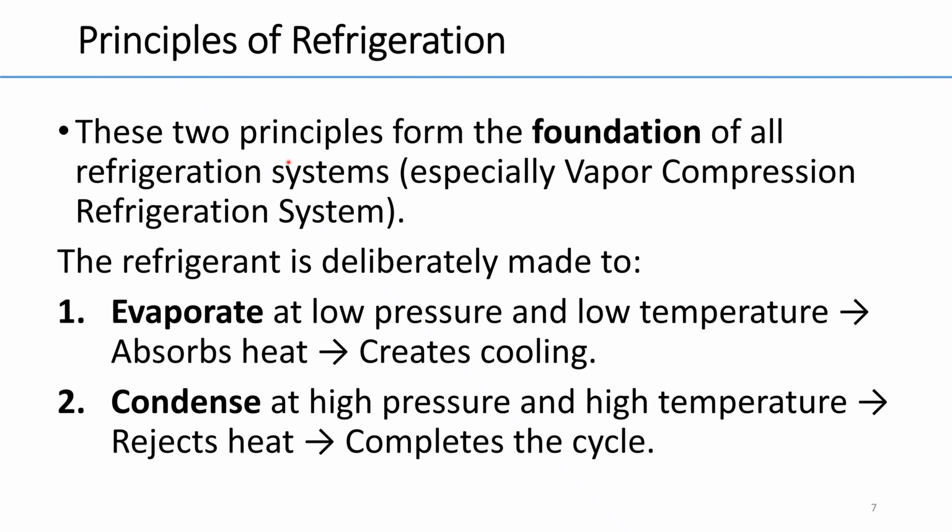The main principle of refrigeration can be categorized into two fundamental principles. Number one, evaporate at low pressure and low temperature, absorb heat, and create cooling. Number two, condense at high temperature and high pressure, reject heat, and complete the cycle.